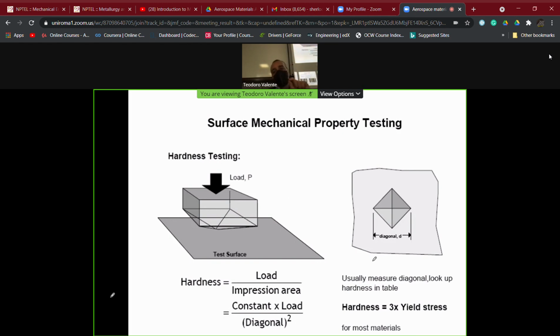And since the variation in surface properties can be localized in a very thin layer, which can be also the length of 1 micrometer, you can understand that if we, for example, want to know the Young modulus of the surface, we cannot use the standard tensile testing that we use to characterize the bulk materials and then have the classical stress strain diagrams, because the answer of the surface in that case is hindered by the answer of the bulk materials.